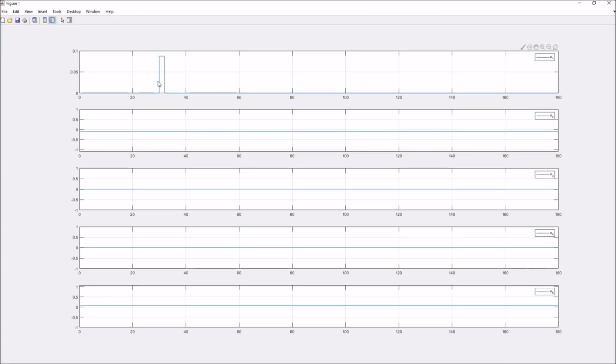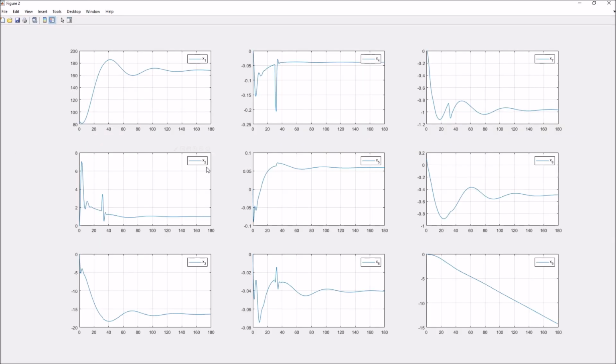So here you go. Here's our aileron pulse. And then look at this here. U4 is sitting here at exactly 0, right? So the engine 4 is completely off. And hopefully what we've done properly is since we handled the saturations properly, the force from the engine that's actually acting on the vehicle is actually 0. And as you can see, we're in big trouble here when that happens.